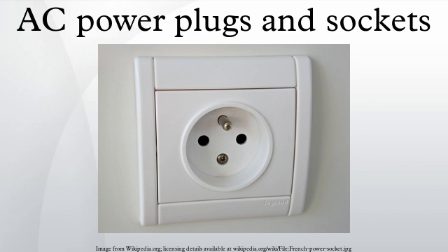The 10A plug has pins which are 4 mm in diameter, the centers spaced 19 mm apart. The 10A socket can accept Europlugs. The 16A plug has pins which are 5 mm in diameter, the centers spaced 26 mm apart. The 16A socket used to be referred to as per la forza motrice or sometimes industriale.